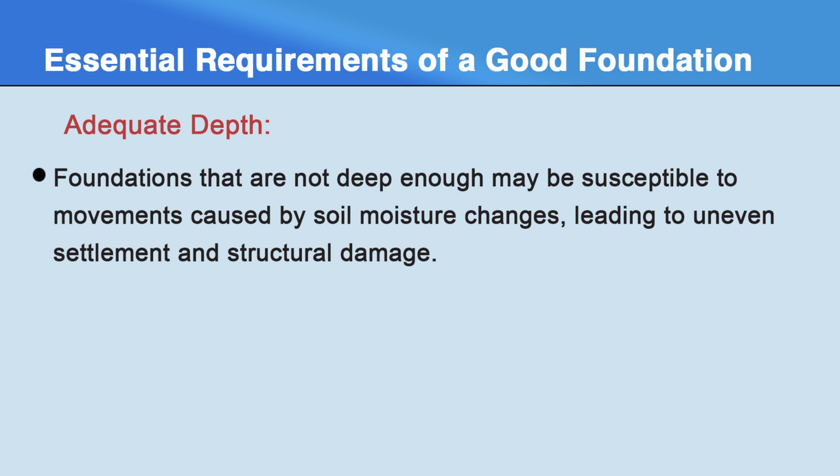Foundations that are not deep enough may be susceptible to movements caused by soil moisture changes, leading to uneven settlement and structural damage. Conduct soil analysis to determine the depth at which the soil remains stable and unaffected by seasonal changes. Foundations should be designed to reach this depth considering local climate and soil conditions.